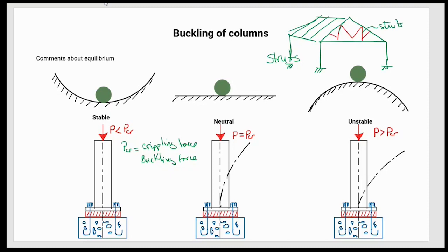And actually, when you design this kind of configuration, these struts are positioned in a way that they only work in either tension or compression. So that's why they're called struts. But they are basically using the same logical approach for failure as those used in columns, in the design of columns or design of struts.